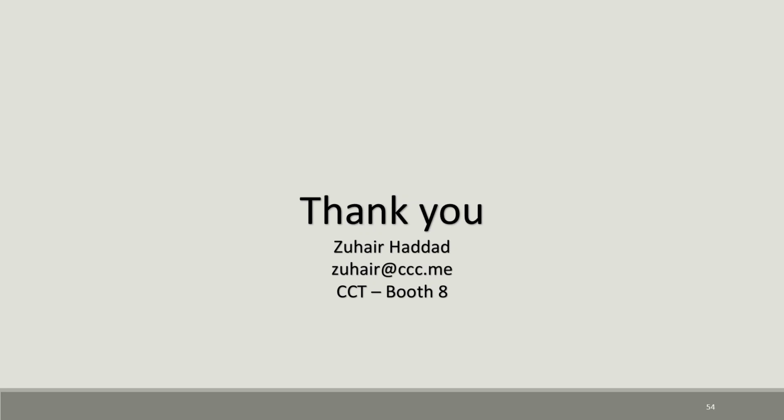Our next question is, did you define the level of information besides the level of detail, like geometry? Yes. When we select the BOQ we're going to use, which is within CCC, it is very standard, which is used by our estimation system. So we decide what BOQ. Sometimes the client imposes it on us. If not, we will do our own. For example, you may price concrete as one item, including the rebar, formwork and the concrete itself supply, or you may do them as 3 BOQs, and we usually do 3 BOQs.